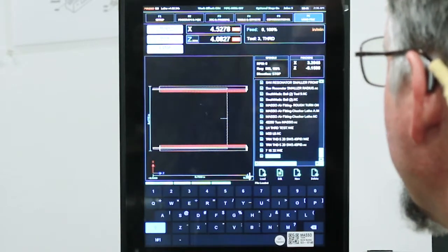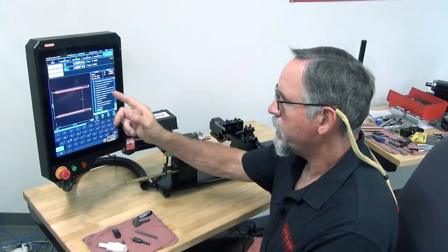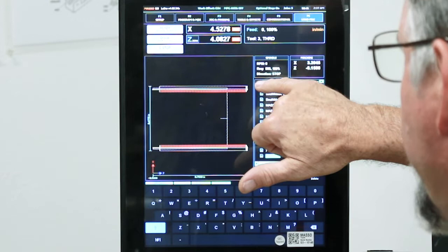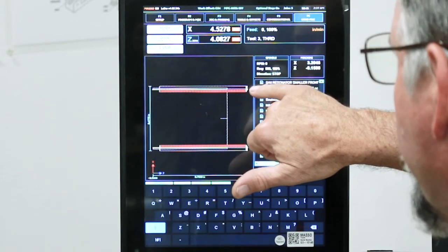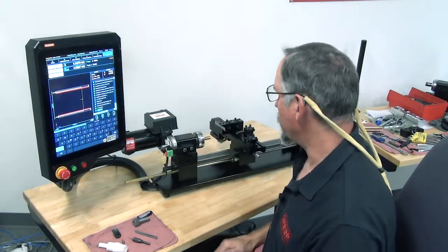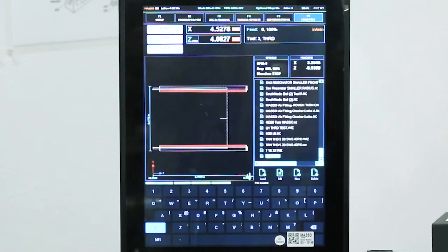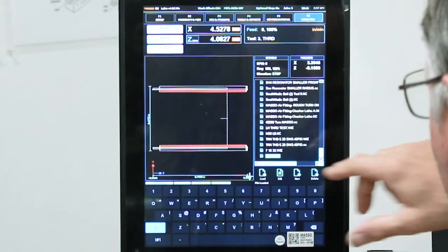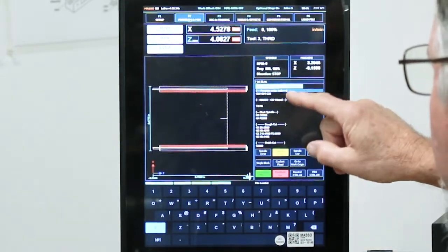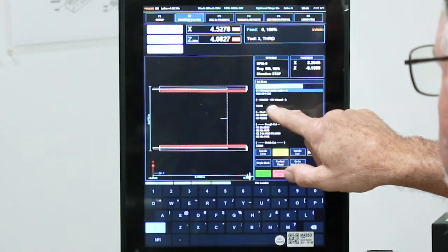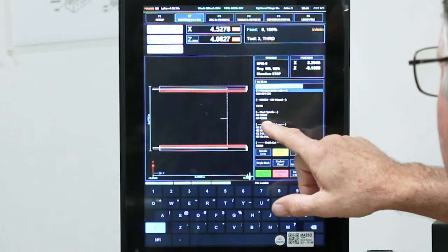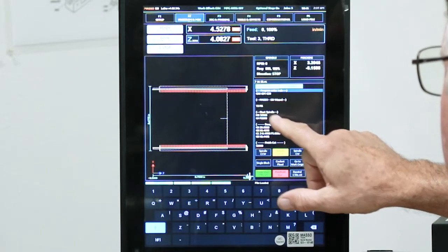Okay, so it shows my turning and my threading. And you can see right here, it's kind of triangle shaped where it's actually coming in at 30 degrees for each successive pass as it does the threading cycle. So I've already tool-eyed this guy. I'm going to go to the F2 page, and it shows tool number 3, M6, change to tool number 3. Spindle speed of 2000.